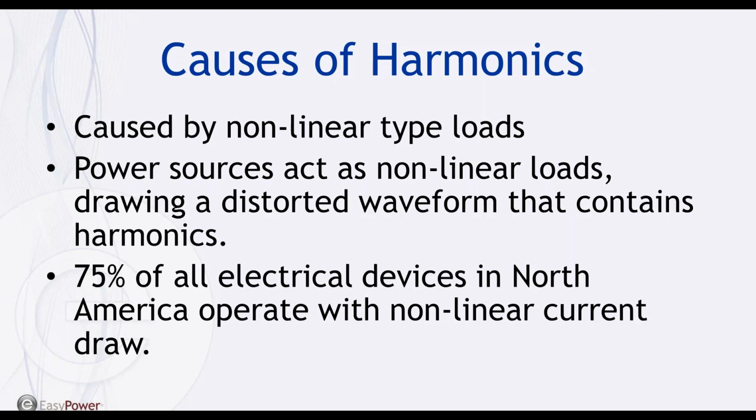As I mentioned, harmonics are caused by nonlinear type loads. Power sources act as nonlinear loads and draw a distorted waveform that contains harmonics. 75% of all electrical devices in North America operate with nonlinear current draw.